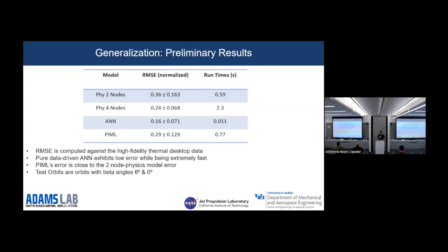Okay, so here are some results, and let me show our thought process behind why we did these comparisons. The first row there is a fixed model that has 2x2 nodes across the entire spacecraft. So in that case, let's say a thermal engineer says, okay, too many orbits, just make a 2x2 grid and just use that. Next one is 4x4 nodes, right?